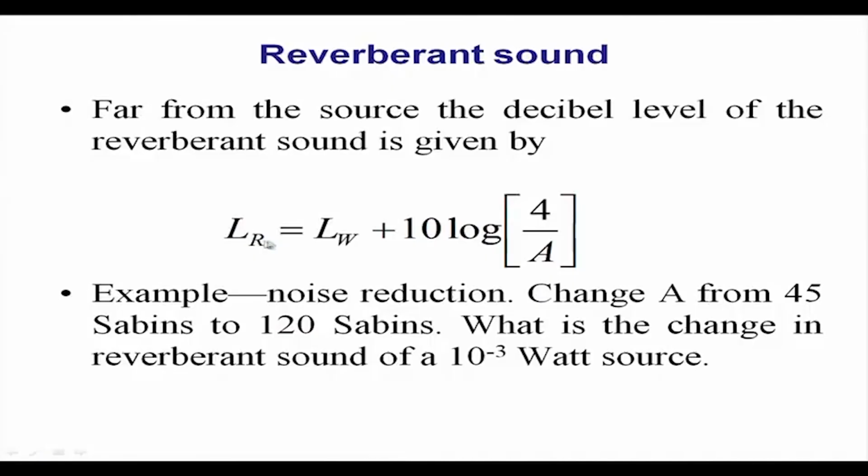LR, the reverberation sound level, is LW, the sound source level, plus 10 log 4 by A.